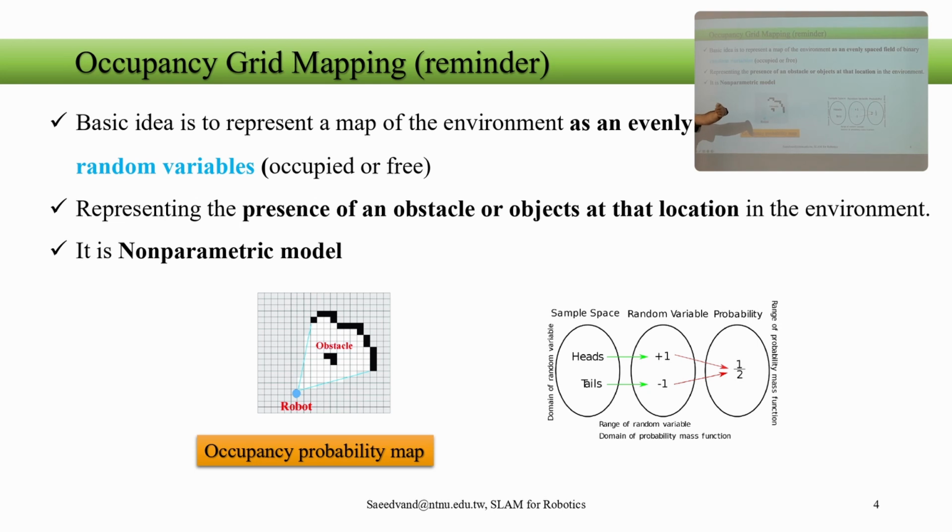Of course, along the line in the middle, there is no obstacle, because my sensor's distance measurement gives, say, 1 meter. So within this 1 meter it's free. I can use that technique to say these cells are all free and this one is occupied. So when you do the scan, you free up to the obstacles, then put the obstacles there. The other parts, in probability form, we say are free.